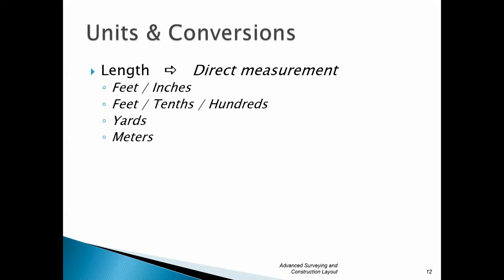So for length, we typically have feet and inches, or feet, tenths, and hundredths, yards, and meters. So architects primarily work in the feet and inch world, and surveyors and layout people very often work in the feet, tenths, and hundredths world. So when I go to grab a steel tape out of my truck, it's graduated in feet, tenths, and hundredths. But all of my plans are going to be marked in feet and inches. So I'm going to have to do a conversion back and forth.